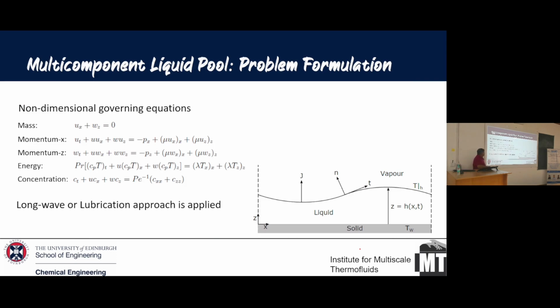So this is the typical non-dimensional governing equations. You can see that you have the mass balance, you have the momentum, just as we did yesterday. You had the momentum in the x direction, and in my derivation yesterday, I think the vertical direction was y, but here it is z, doesn't matter. So you've got the momentum equation in z, and you can notice that I have not done anything with gravity. I have not done anything with gravity because this is such a thin film, I'm not really bothered much about it. In fact, this is not completely correct. When you have evaporation, you will have buoyancy effects come into the picture. I'm ignoring those effects.